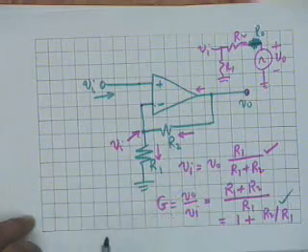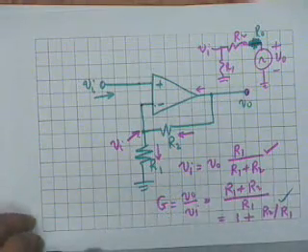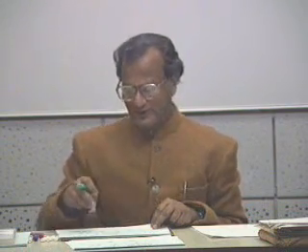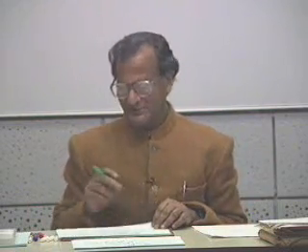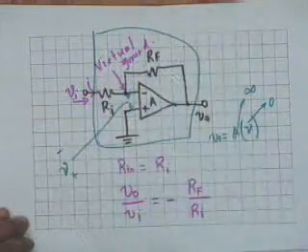So why is it so? Why do we connect resistance in this case and not in that? We want a non-inverting gain, then this is the configuration. We want an inverting gain, then the previous circuit that you drew, this is the configuration. Why do we do that? We want to get a certain gain, and so we determine the gain through two external resistors, RF and Ri.